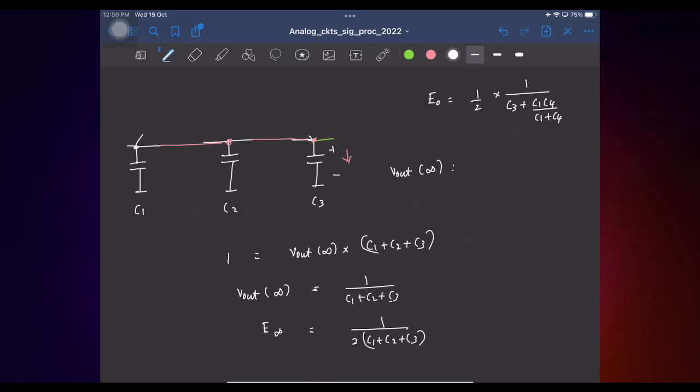For example, in this network, if there were any node connected to ground, then the capacitor would get a path to discharge. Basically, if it is ground, that capacitor is not in the picture at all. If you are saying you have a switch and connect it to ground, that is not what we are considering. We are taking only linear time-invariant networks. We haven't talked about time variance yet; we will come to that later. Is it possible that only partial charge is lost? You think about it. It will not happen.